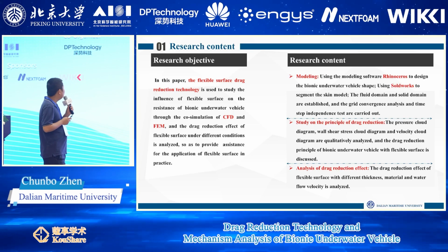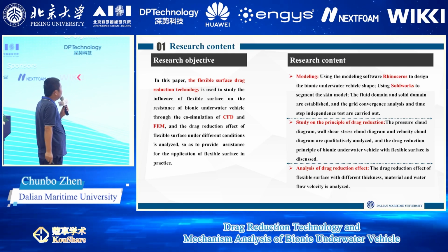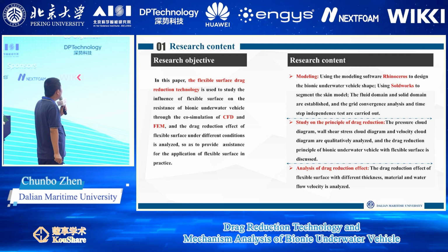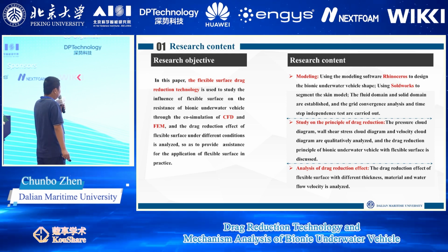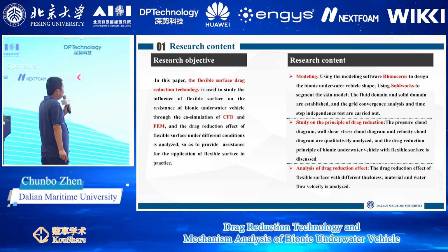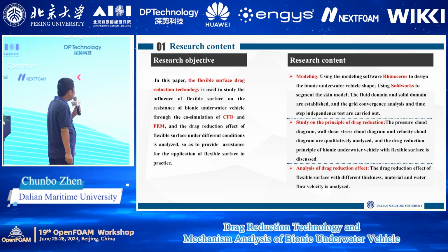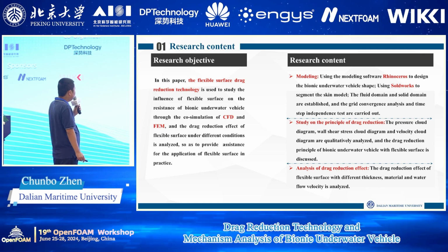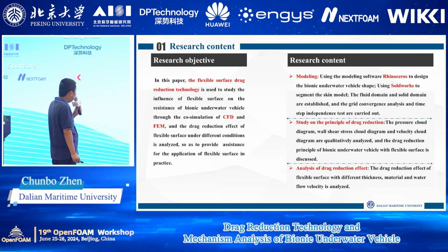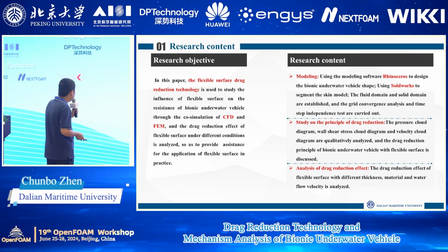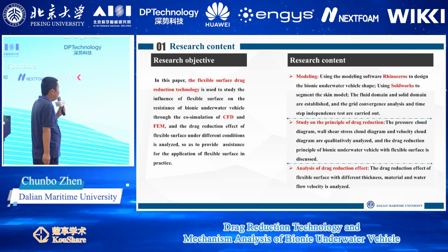In this paper, flexible surface drag reduction technology is used to study the influence of flexible surface on the resistance of the bionic underwater vehicle through co-simulation of CFD and FEM. The drag reduction effect of the flexible surface under different conditions is analyzed, so as to provide assistance for the application of flexible surface in practice.